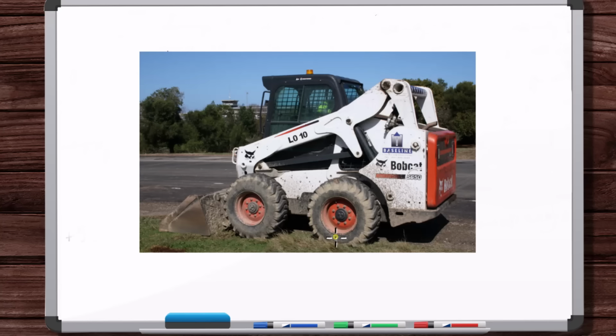Okay, let's take a look at this bobcat here. With a free body diagram, what you're doing is you're taking any component off of this bobcat, any component or any group of connected components. And then what you can imagine is you bring that component or components into empty space. Empty space meaning there's no planets, there's no forces on it, and it's just suspended in nothingness. So let's just say we took this component here.